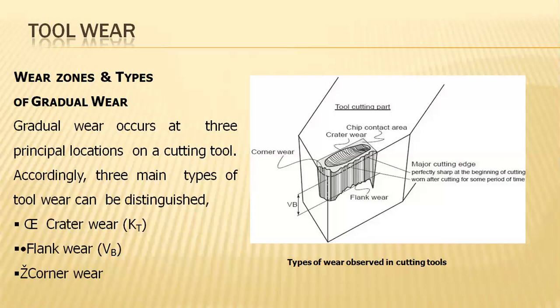And secondly, the flank wear. So this is the flank wear, which is utilized for a major cutting edge, which we normally call the major cutting edge, which will give the perfect dimensions over the surface finishing of the work parts, because this will have the sharp edges from the cutting even after a particular time period, by elevating a minute or micro level of deformation with respect to the slant angle of the tool bit.